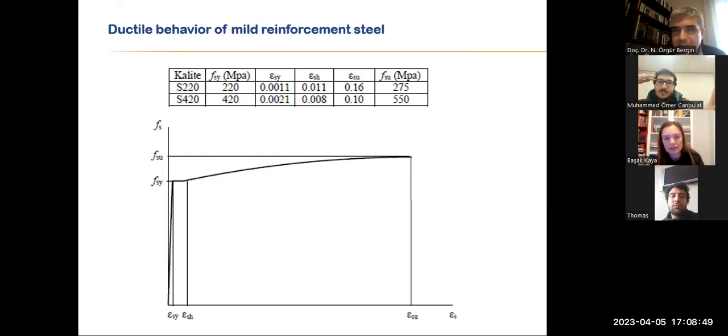But in design, you estimate your seismic forces, and then you calculate your rebar requirements by these values. So even on the seismic loads, you don't design your structure to go all the way to this region. You design it so that it will happen here. Yes. So what is bigger than the seismic forces in this case? What else is going to happen to the structure to have me go all the way to this part?